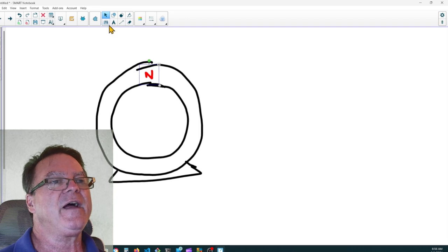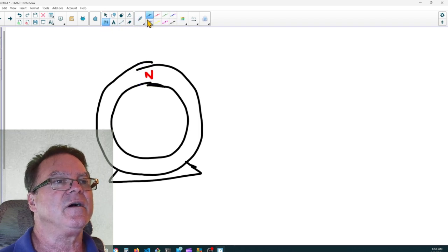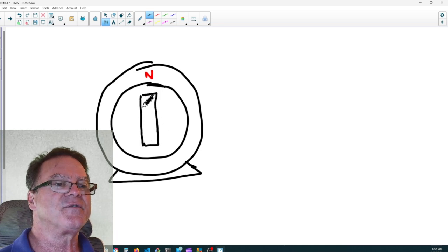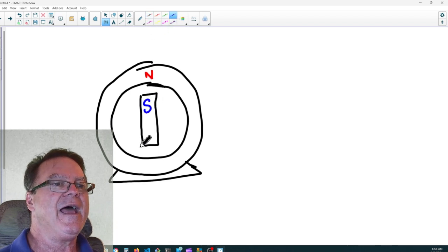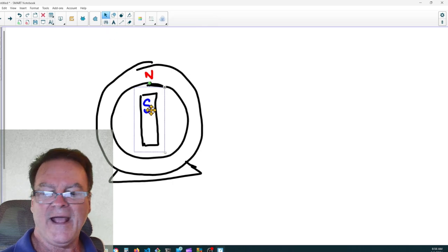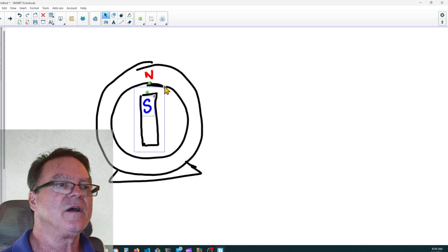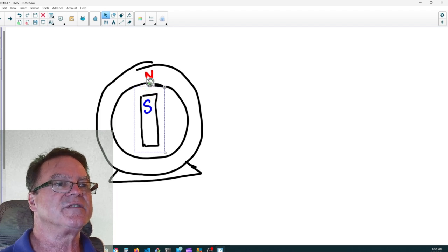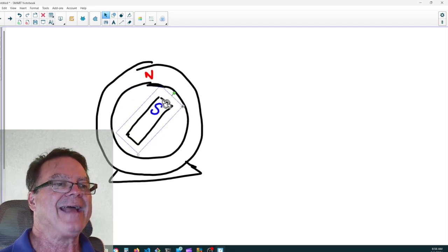But if I have a stator, if I have a rotor, if I can put a rotor in here, and I can use slip rings, and I can use a DC source, I could feed this through those slip rings to cause a south pole to be here. And when that south pole and that north pole are locked in, well, there we go. When that happens, this rotor is going to rotate at synchronous speed.